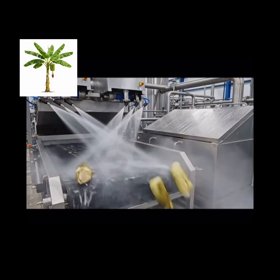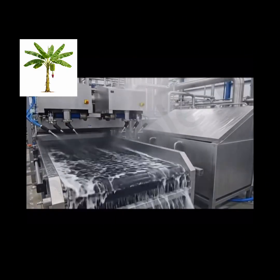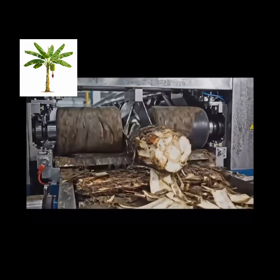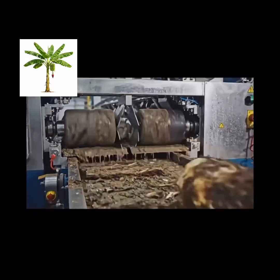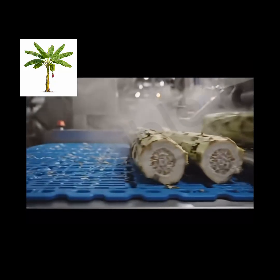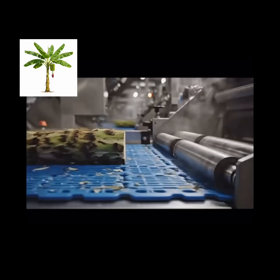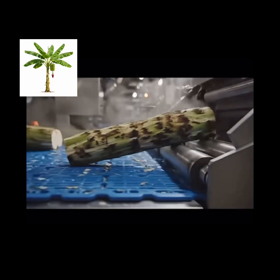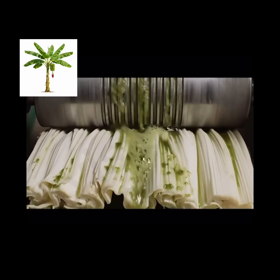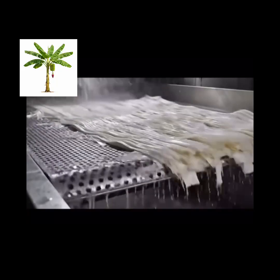At this point, the fibers are strong but stiff. Natural plant gums, lignin, and pectin still bind the fiber bundles together. To make the fibers soft and flexible and suitable for spinning, degumming is required. Degumming can be done chemically or enzymatically. Chemical degumming typically uses controlled alkaline solutions. Enzymatic degumming uses specialized enzymes that break down non-cellulosic materials without damaging the cellulose fibers.